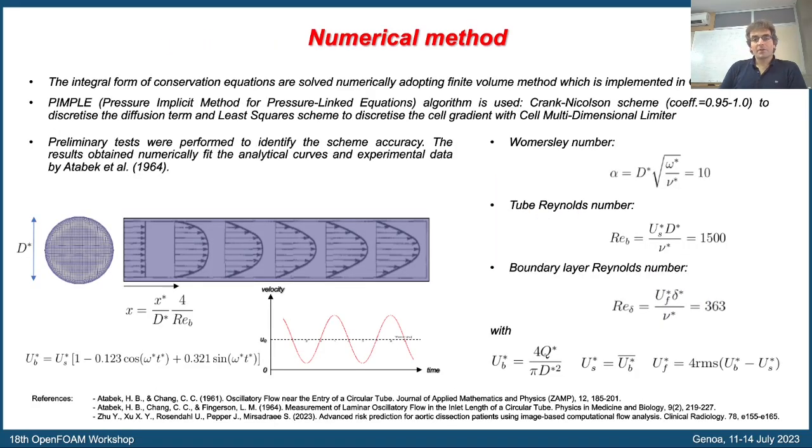We have used, of course, OpenFOAM to carry out the simulation. They are quite fast simulations. They took a couple of days each. And we have used the PIMPLE scheme. First of all, we have verified the second order accuracy, considering a problem which looks like the problem that we were going to investigate. We perform a direct numerical simulation of a pulsating flow in a straight circular pipe with rigid walls